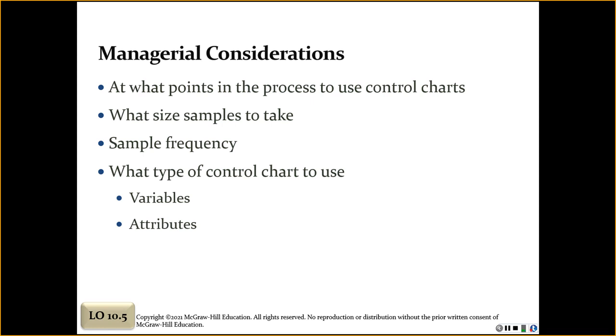Either the diameter can be measured, and a mean chart can be used to control the output of that part. Or the part could be inspected using a go, no go, good or not good, which would indicate whether the part is within whatever specifications the organization sets, without giving it an exact dimension. For this, you can use the P chart because you're just basing it on attributes and not actual numbers or factors.